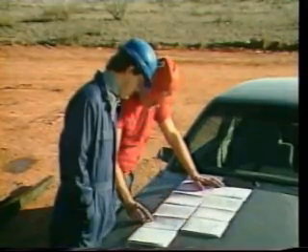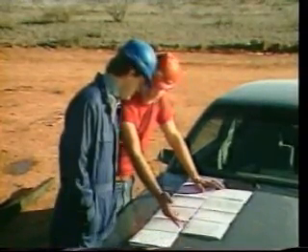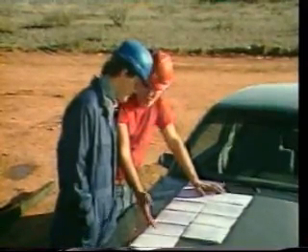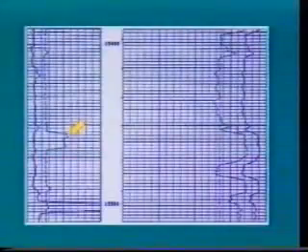In other cases, the effects of drilling with regard to log evaluation can be detrimental. For example, when the drilling process has created an irregular borehole, or the filtrate has penetrated deep into the formation, some logging measurements can be erratic, insensitive, or difficult to interpret.